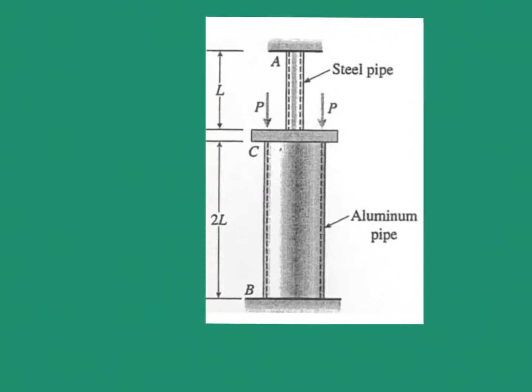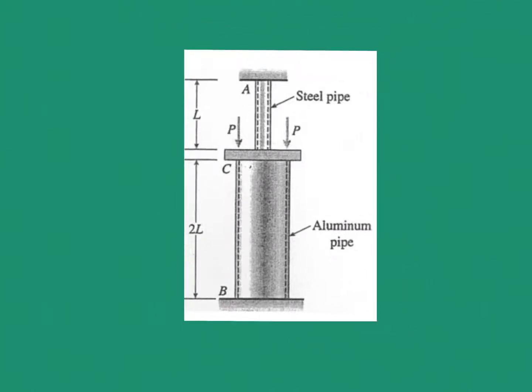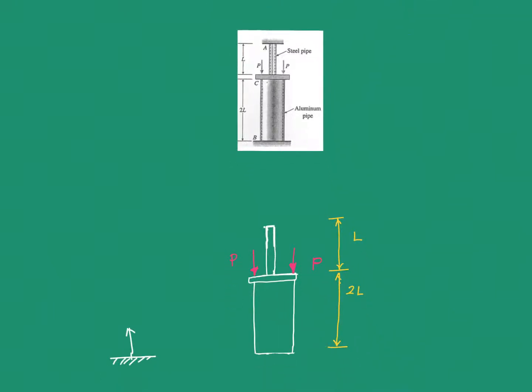If you look carefully, this is a statically indeterminate problem. There are a lot of ways in which you can solve statically indeterminate problems, but the one which I'm going to pick is relatively simple. You don't have to learn these methods by their names, you just understand the concept. What I'm going to do now is remove this particular support from here and replace that with a force, or a reaction, at that point. So the problem I'm going to solve now will look something like this.